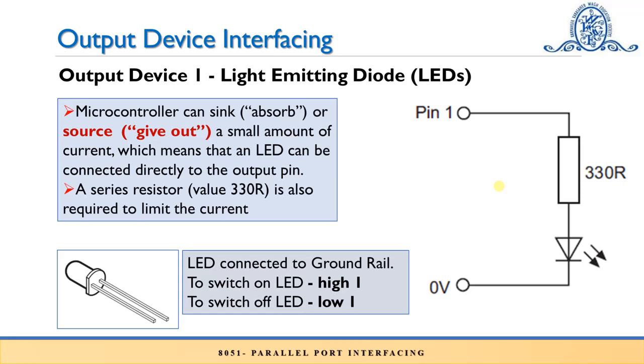Now, when we have to connect the LED with the microcontroller, we have to take care of the current which is carried by the LED. So we have to limit the current by using a current limiting resistor.